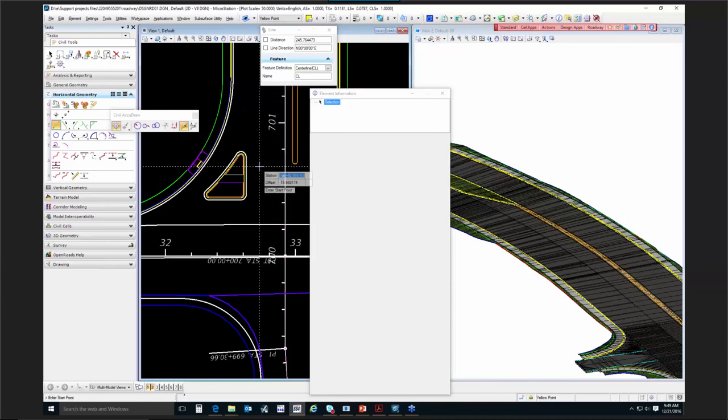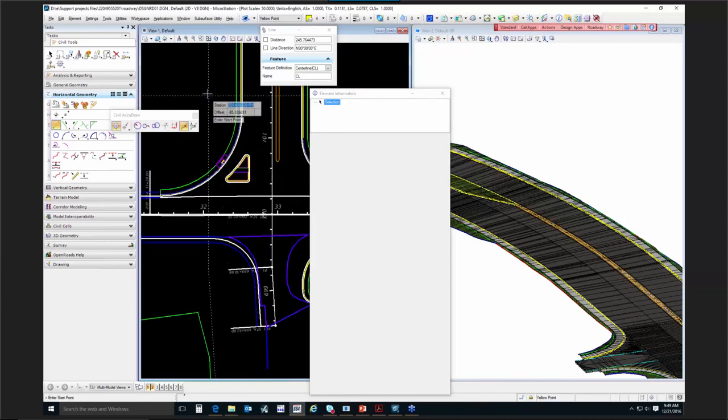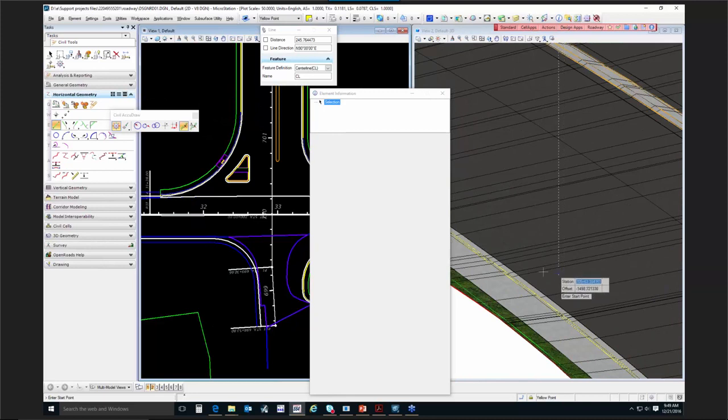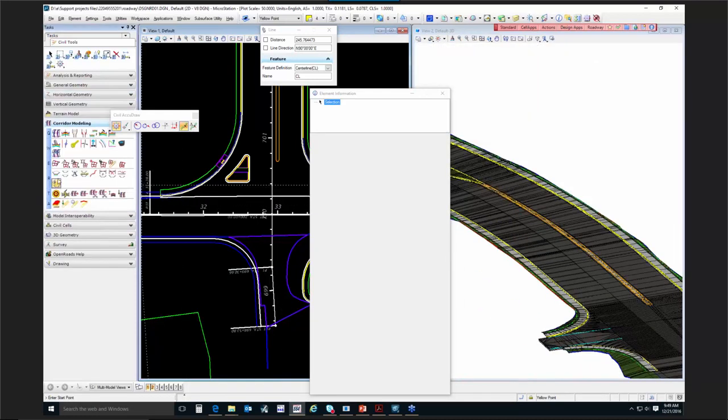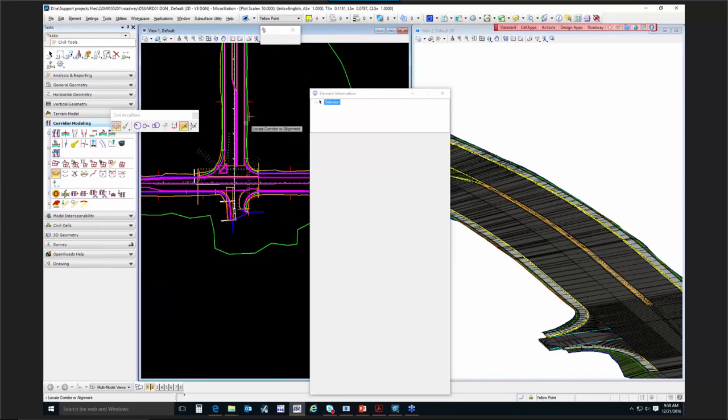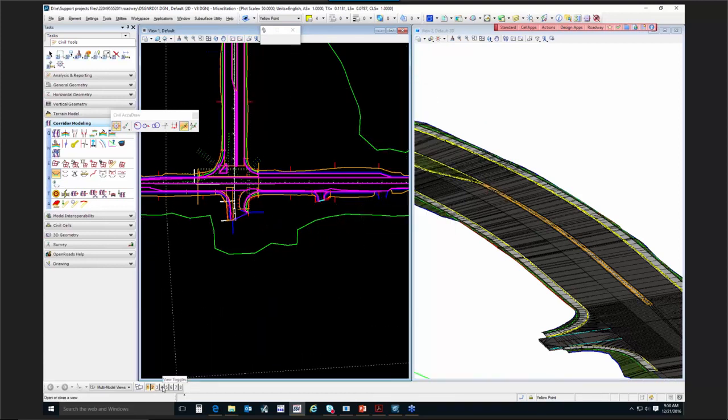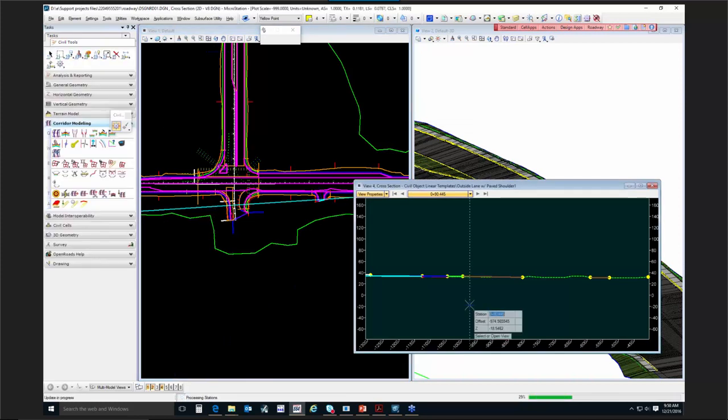that I want to reference off of to here, now I'm tracking station offset in the plan, but when you go over to the model, you can actually get station offset in the model as well. And if you were in a cross-section view, let me open up a cross-section view real quick. I want to show one more thing here anyway. If I opened up a cross-section view, let me turn off this and open this model over here. And once it processes this, I can also do station offset and elevation in this view as well.